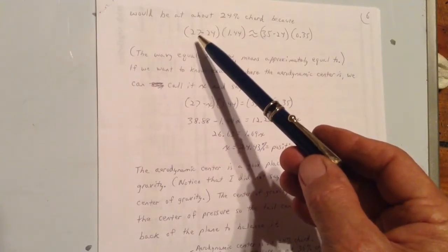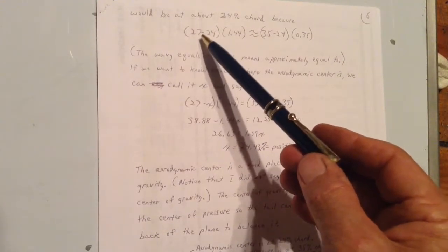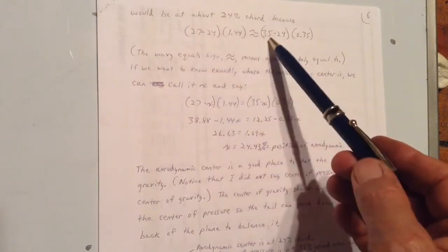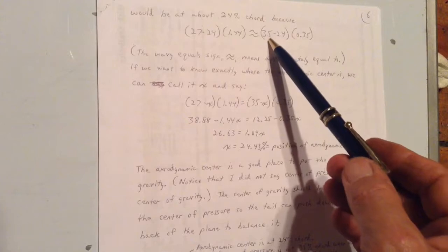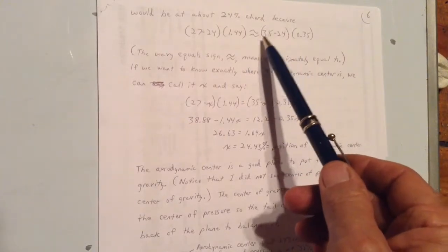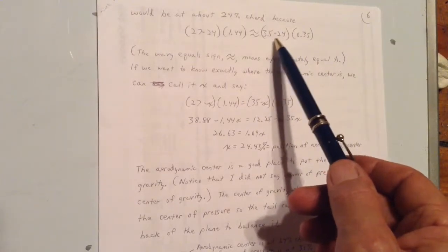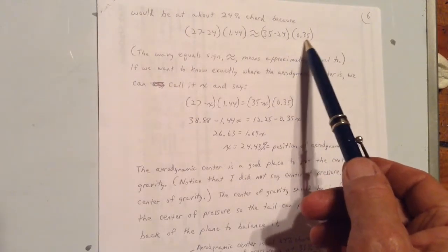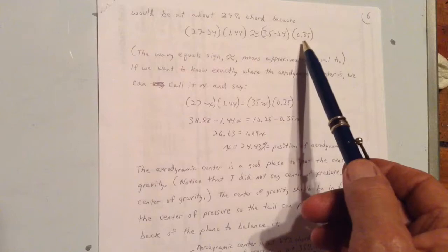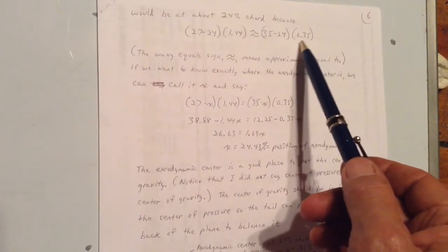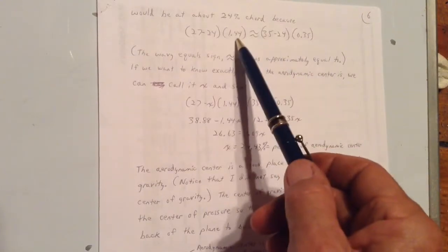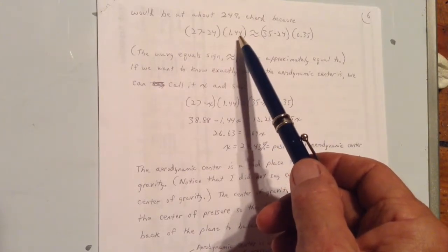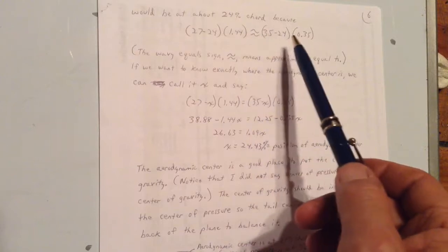Center of pressure was at 27% of the distance between the leading edge to the trailing edge for a high angle of attack, an 18-degree angle of attack. We were told it was at 35% of the way back from the leading edge to the trailing edge at a lower angle of attack, 3 degrees. We were told that the coefficient of lift is 0.35 at the lower 3-degree angle of attack, and that the coefficient of lift is 1.44 at the greater 18-degree angle of attack.